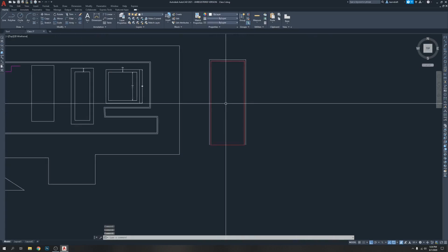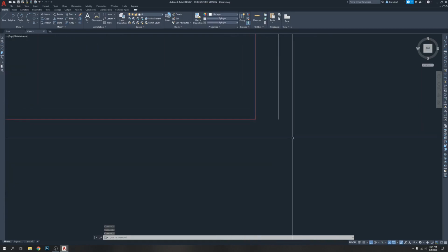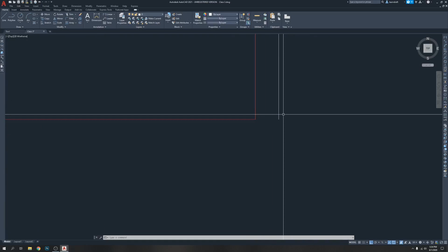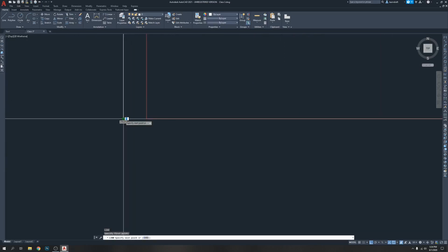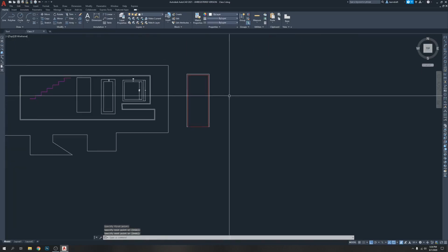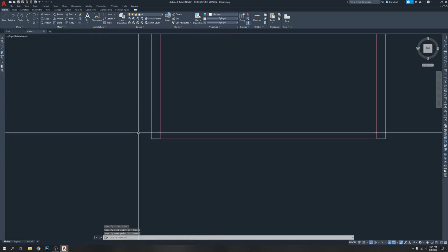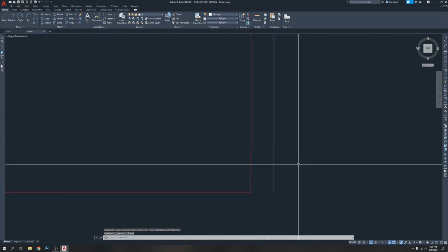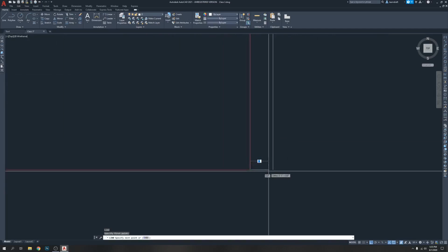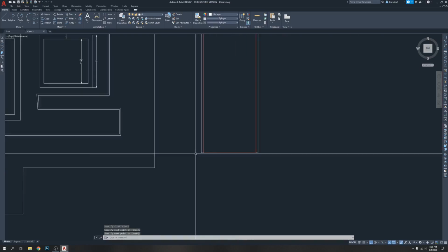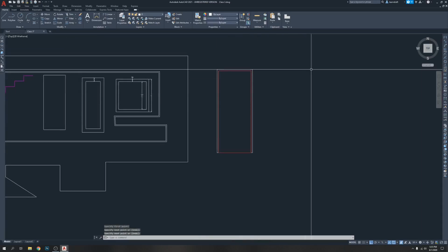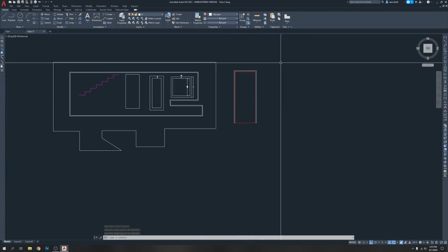It's gonna go to back. Now if you want to draw a line here, you can draw a line here. L, enter, enter, L, enter. Actually it was confusing, let me make it clear. So L, enter, click here, click there, enter, again enter to repeat the command, click here, enter. So now you're good, the door is there. So now I hope you understand about polyline and multiline.